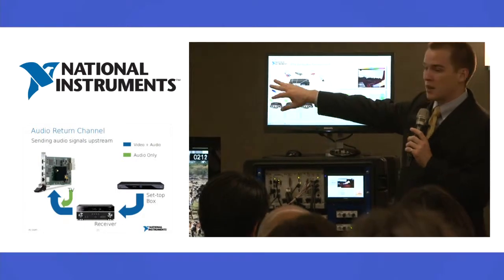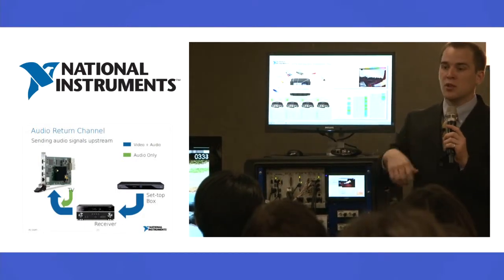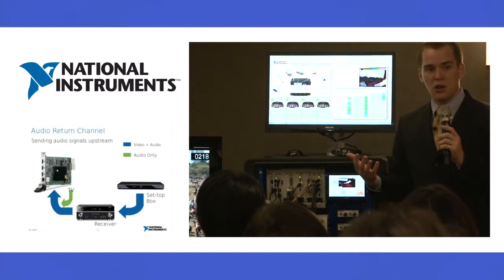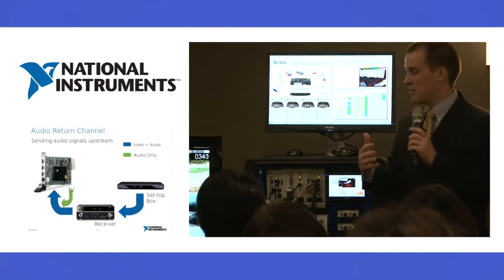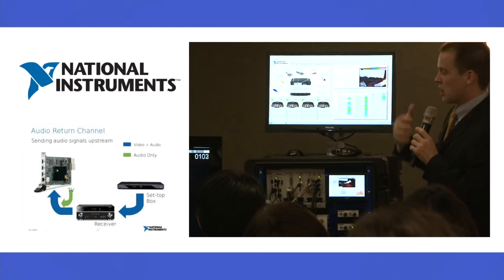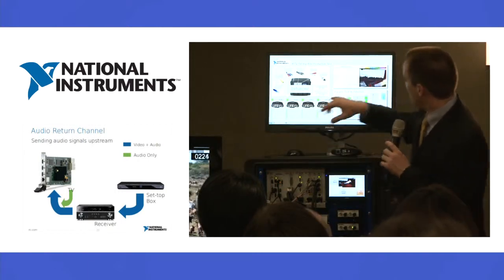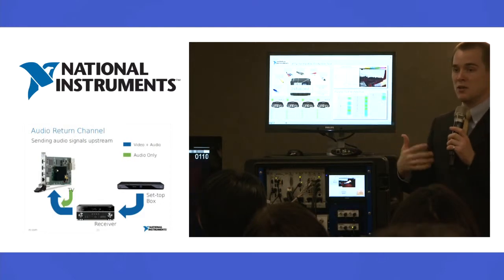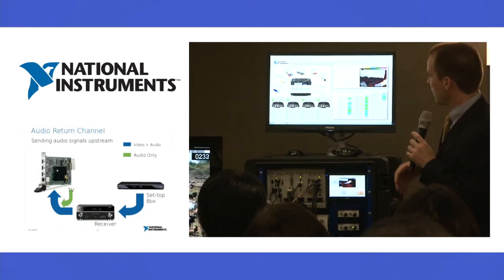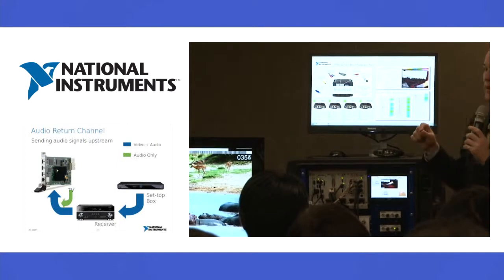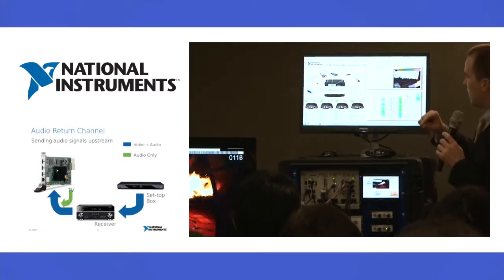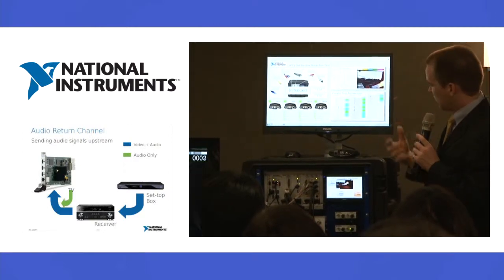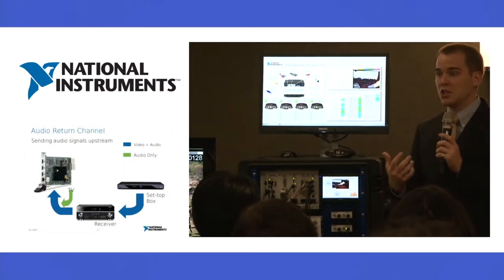Say, for instance, composite video, we're going to make sure that the horizontal timing of the signal is correct. It is an analog waveform. You need to make sure that the horizontal timing is working. We're also doing a color bar test. So it's hard to see here, but there's a color bar at the top of the image, and we're making sure that that color bar is represented accurately. It's very similar for component because it's a similar protocol. Also for HDMI, we're doing a color bar test, a blockiness test, making sure the audio of HDMI is working properly.